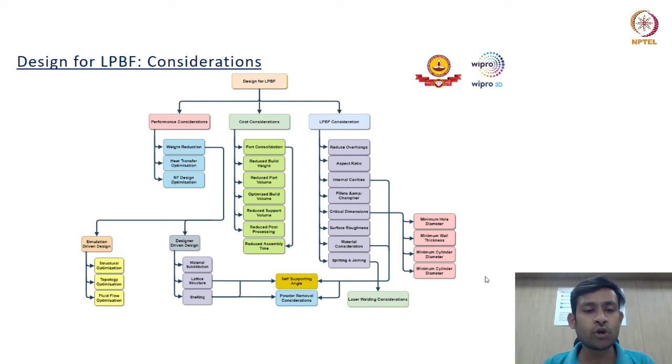In the next slide, I will show you a small example of the simulation driven design, where we will do topology optimization of a structural component for an electric vehicle called an upright. Designer driven design is something that we have already covered. So till now, the feed cluster case study that I had shown you, the designer has to identify the design space and non-design space, and the designer has to develop the features, and later on the FEA is done based on the end application conditions. But in simulation driven design, things are going on simultaneously. The design is being developed based on the FEA guidelines.